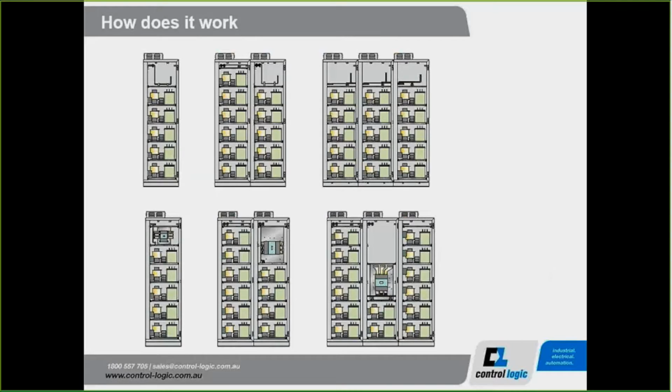So what this slide shows here is a power factor correction unit cabinet with the doors taken off so you can see the different sides. What you'll be able to see, there's different size power factor correction units here. You can see going from left to right, you've got a single tier, a double tier, or a triple tier. Each of these tiers has trays, or steps as they're otherwise known. What you have on each tray or step is basically a contactor, fuses, a reactor, capacitors, and some discharge resistors.